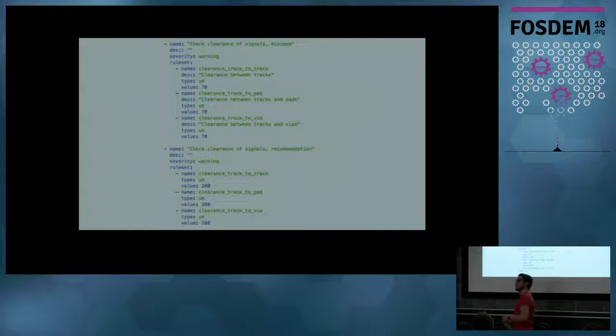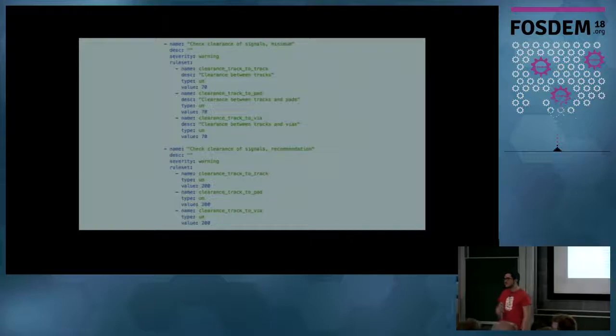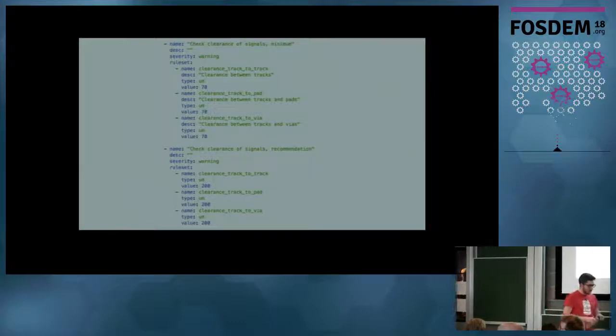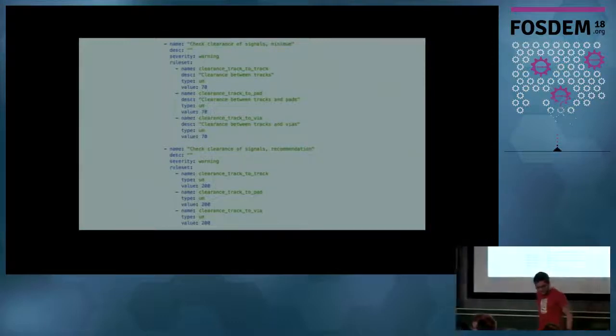Just one comment, Tom. I just think there's a difference between board layout. We could do per net clearances and keep that, right? But those aren't what the manufacturers care about. He's talking about manufacturing. You know, when you go to a fab house, there are guys who can do really high accuracy stuff. There are fab houses that can't, depending on the equipment they have. I think that's the difference between the two.